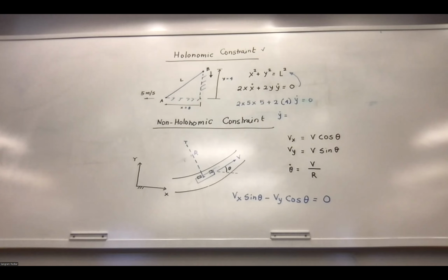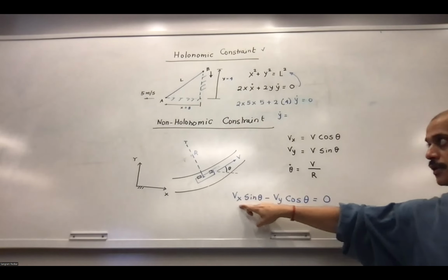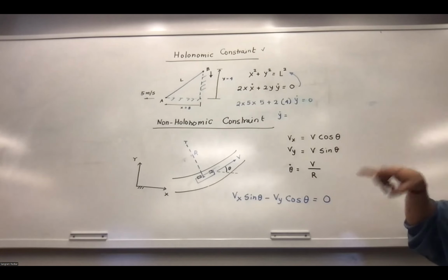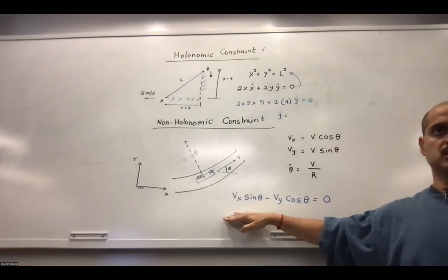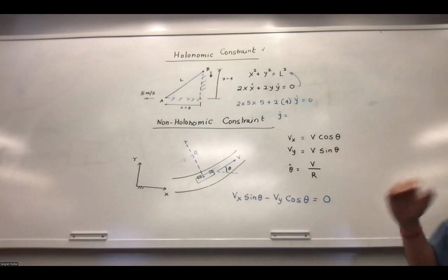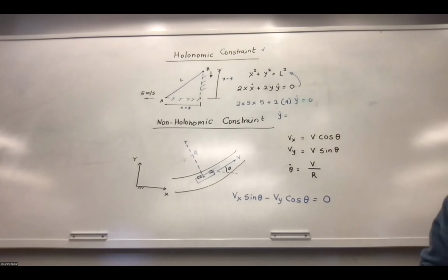If you have an omnidirectional robot with the mecanum wheel, that we'll talk about, then basically you can turn wherever it is. So you need an omnidirectional robot to satisfy the holonomic constraint. But a non-holonomic constraint means if you have a ground vehicle, you cannot turn the ground vehicle without going forward. You have to go forward and turn. You cannot turn wherever you are standing. So please remember this, because this is not explained the way I tried to discuss it over here.